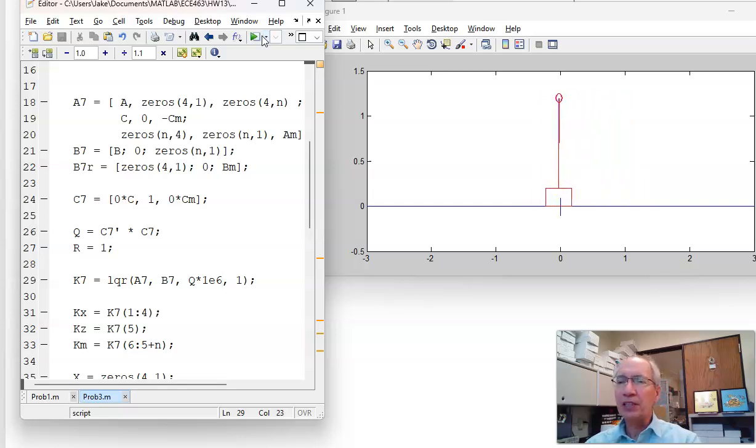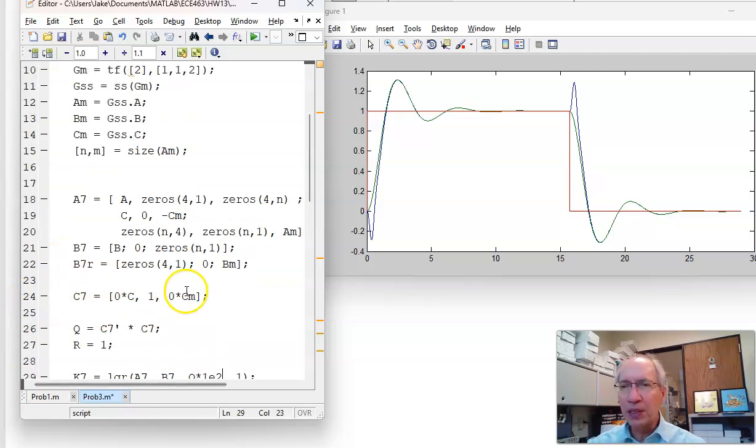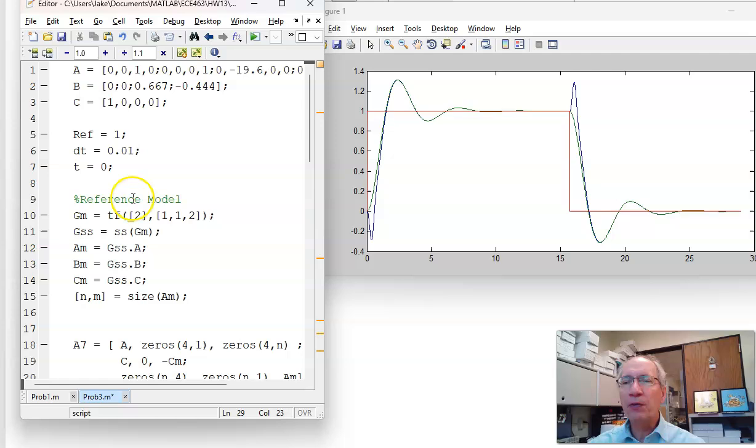There is a caveat. I am getting fairly high gains, and it's just not tracking all that well. Part of the problem is the plant is non-minimum phase. To go left, I first have to go right, get the pendulum to start leaning, and then come over. So the reference model isn't really the best. It's also a fourth order plant, well, fifth order with a servo compensator, trying to make it behave like a second order reference model.